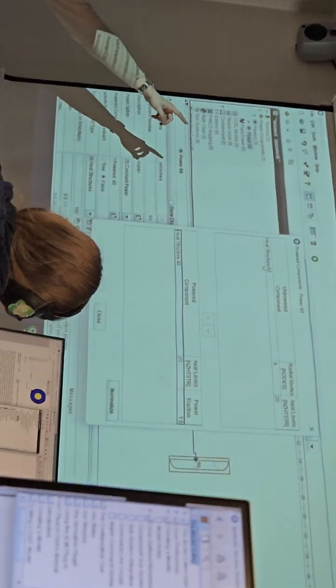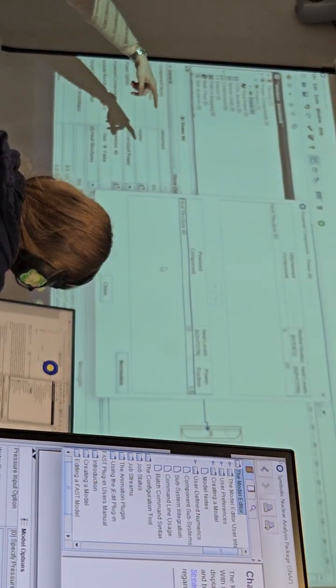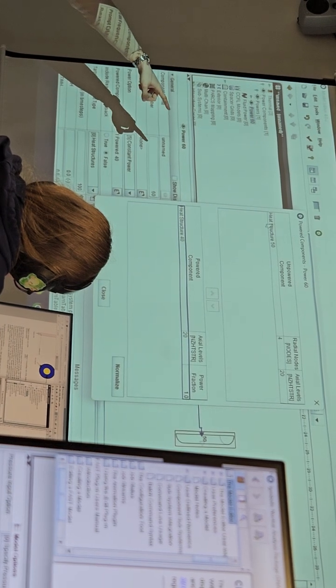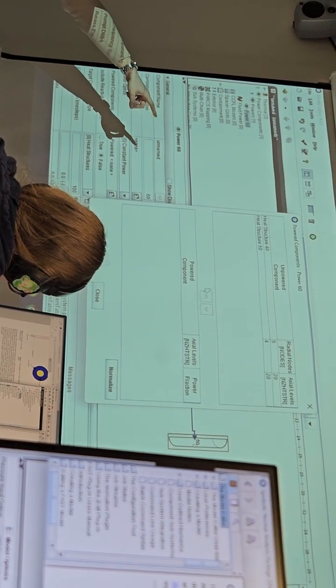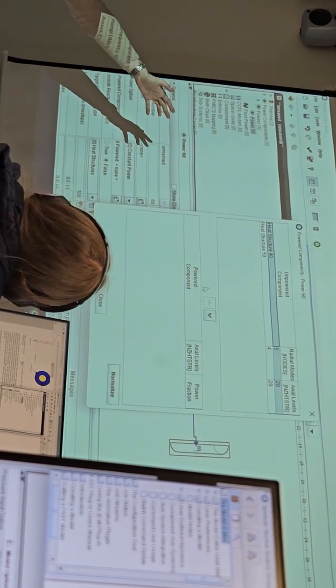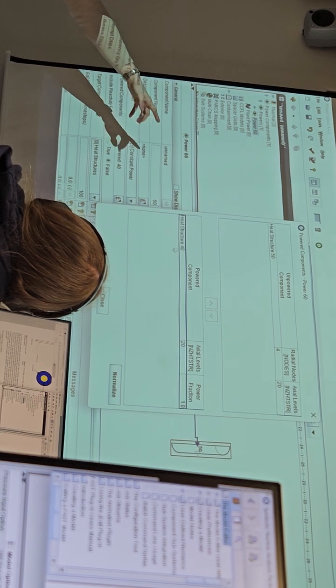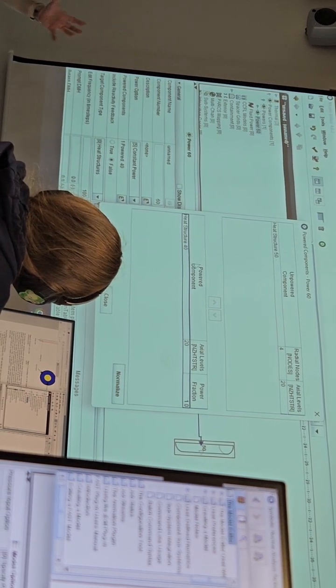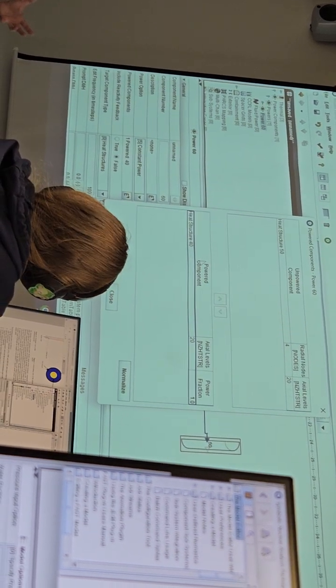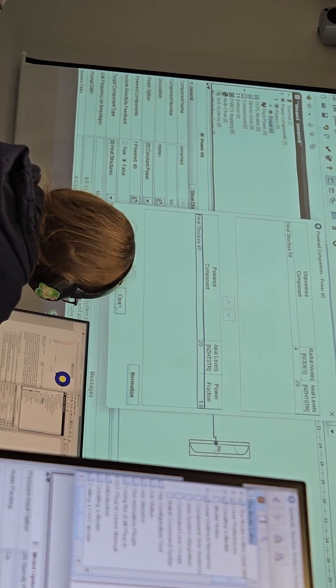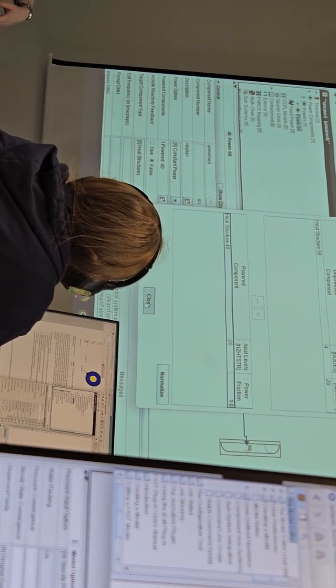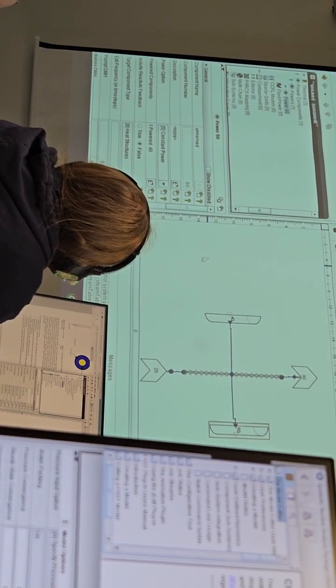And here you have to just click on the correct one, heat structure number 40, it was on top here. If you click on that, click on this arrow, it will be powered. So then the power component is connected to the heat structure component. Okay, and close.